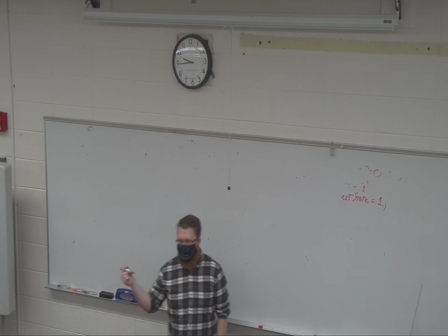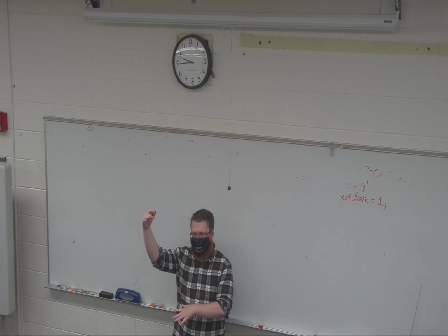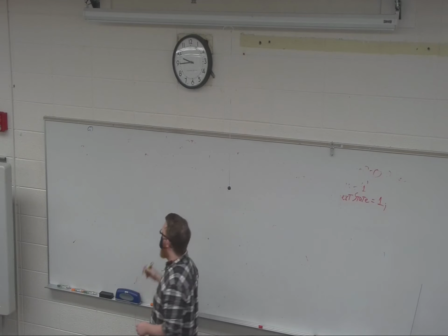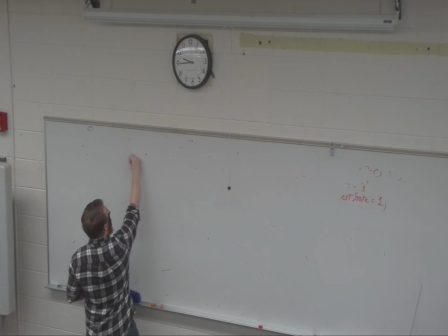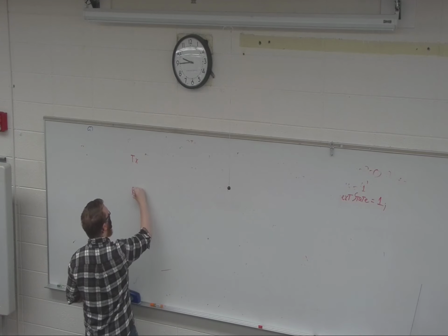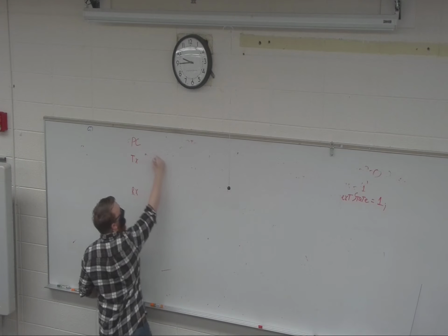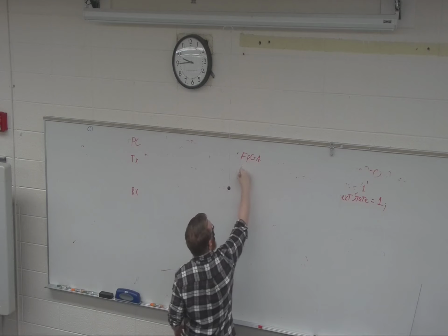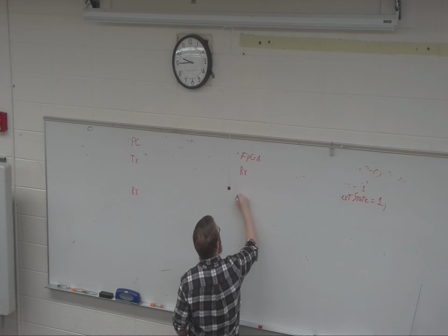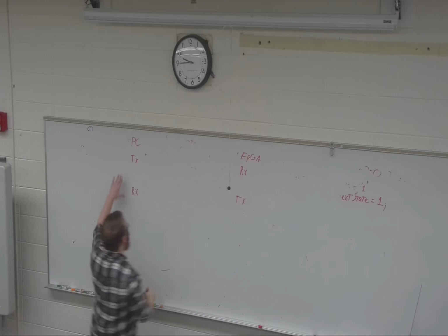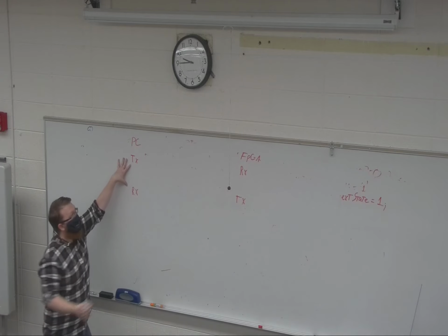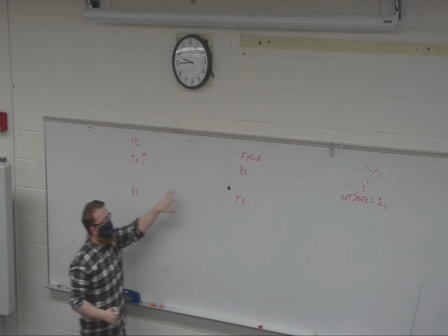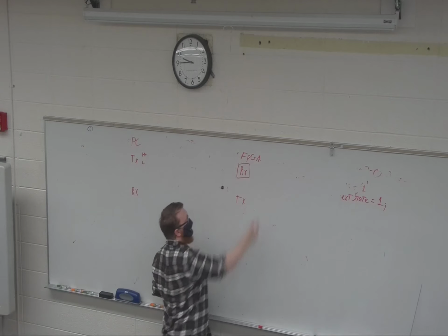What serial means is it's all coming in one line. It's not parallel, right? And it's what we call UART. Now this is a very old school style of communication where you have 2 dedicated lines. This will be on the PC, and then over here we'll put our FPGA, and they're going to be wired together with 2 lines. Again, it's digital, so it can only be high level or low level logic. So what we're building is the receiver.